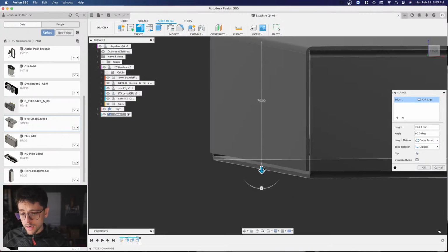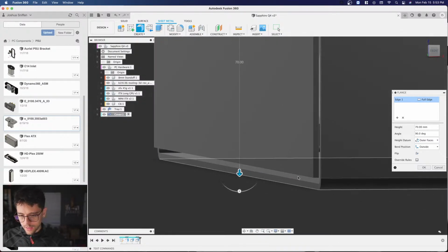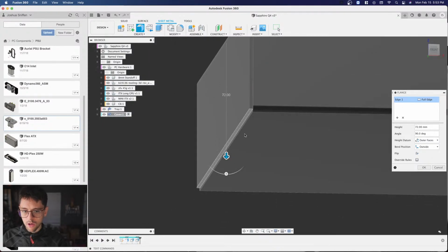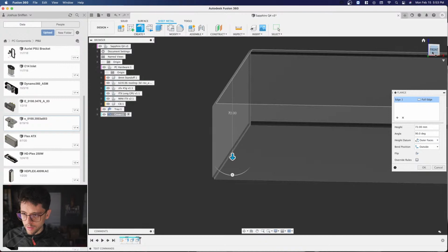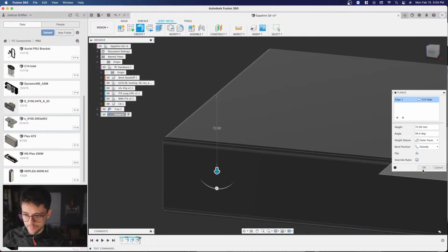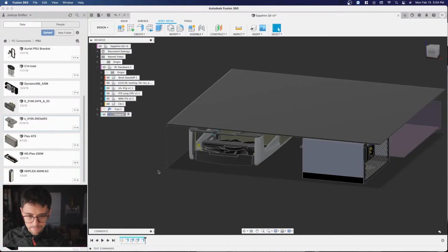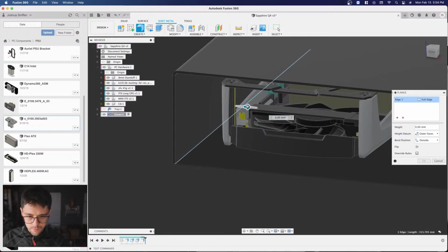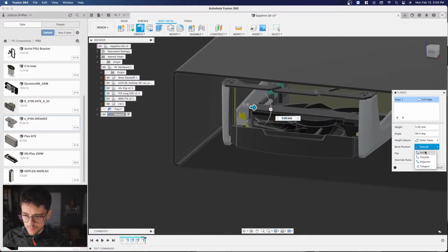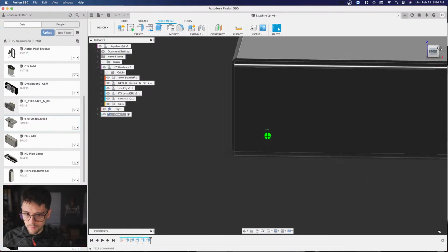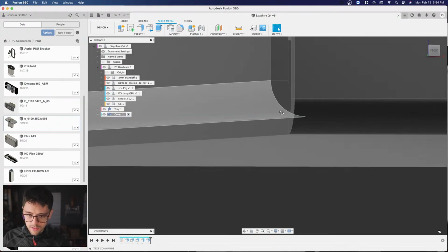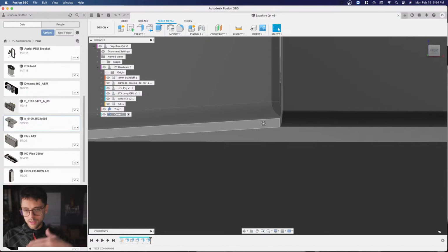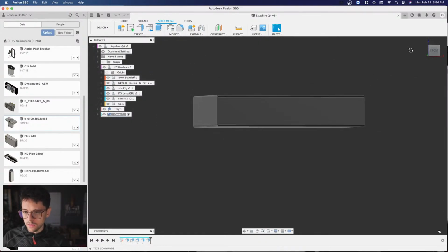I got to bring it to the floor. You notice when I click on the floor right here, it doesn't go all the way down, and I believe that's because, yeah, it wants me to go all the way to the bottom, and then when I bend it out, it should make the appropriate flange. Let's test that though. We're going to hide the tray. And we want this to be 12. All right, and you can see that our flanges mated how we wanted. We wanted to touch that bottom tray, and it did. So let's do the other side.